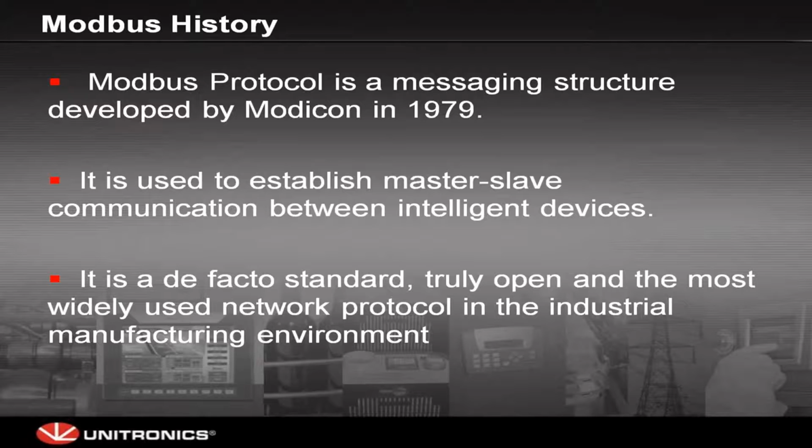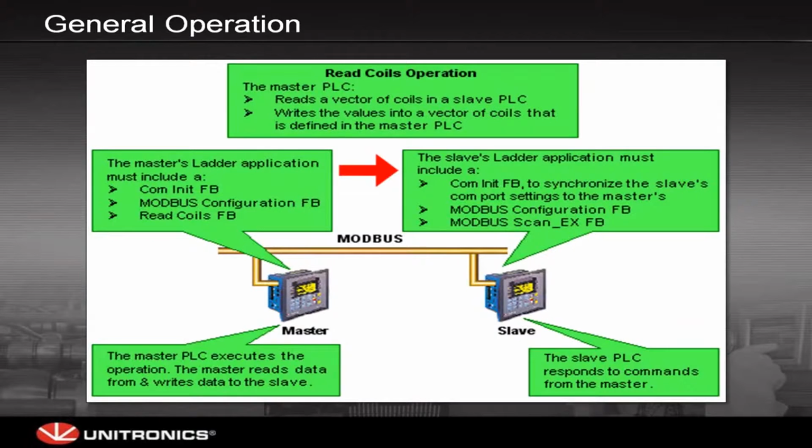But it's really, as I said, an open standard, so you can talk to pretty much any device that supports the MODBUS protocol. We would be able to talk to that either as a master or as a slave. Unitronics can support being either of those on the MODBUS network. And let me just say real quick too that we have a master-slave relationship.